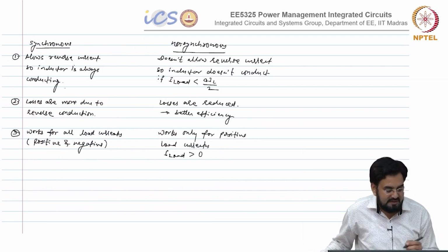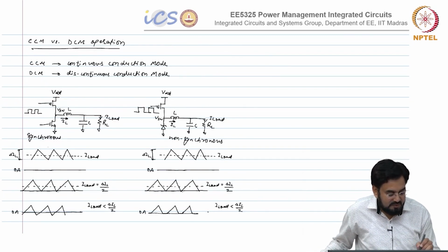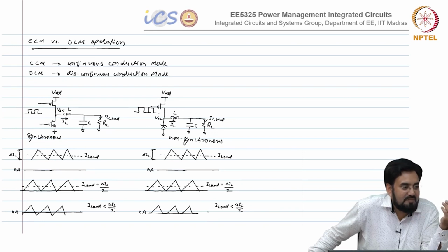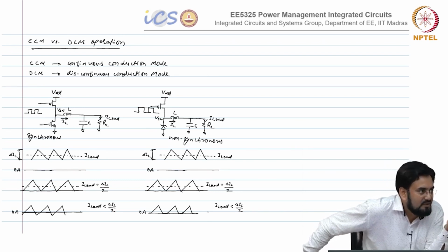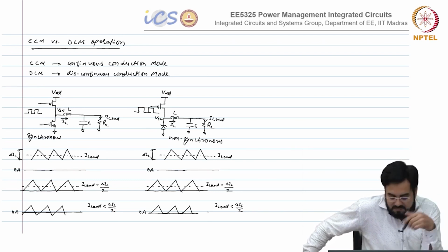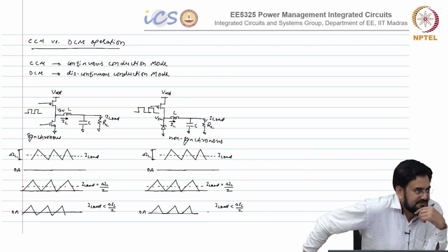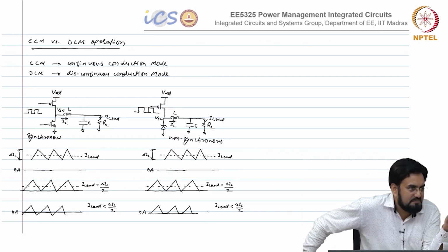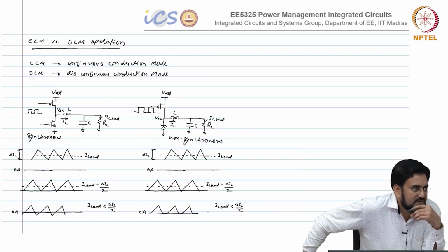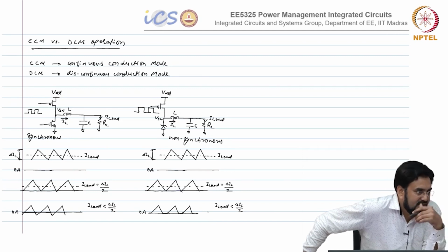So, ideally, I mean, you would prefer this NMOS because of 0 forward bias, or you can say it is not 0 forward bias, but it is an IR drop. So, it depends on load, but if RDS on is very low, then it will be much lower compared to your diode forward bias. Even if you use a Schottky diode, you cannot achieve maybe better than 300 millivolt or so, but here you can achieve 100 millivolt or less, depending upon what RDS on you choose.